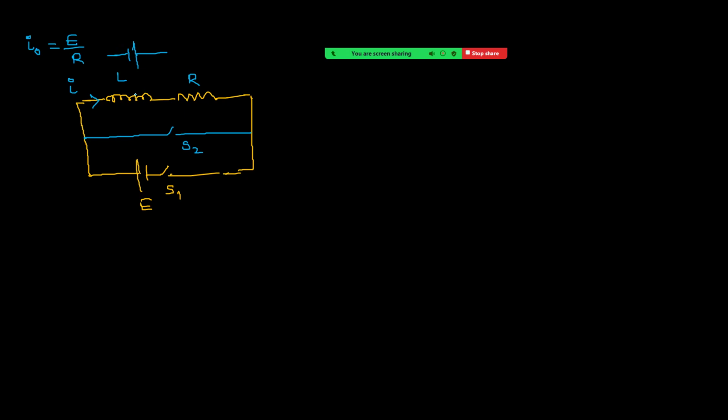Okay, right. Now take Kirchhoff's second law for this loop. So now it is just like there is a battery and a resistor, right? Now see what happens. Suppose we are starting from here and moving like this. So we are moving from where to where? From low potential to high potential. Low to high. It is L into, see carefully, I am writing here minus di by dt.